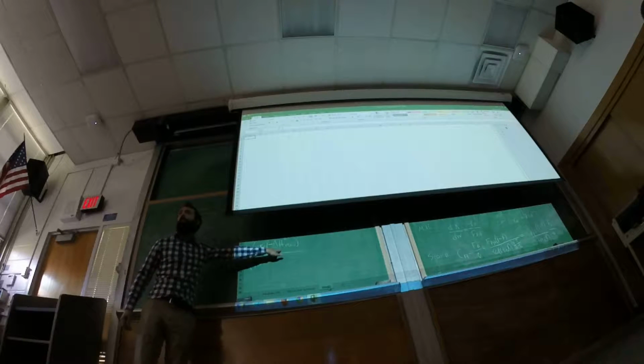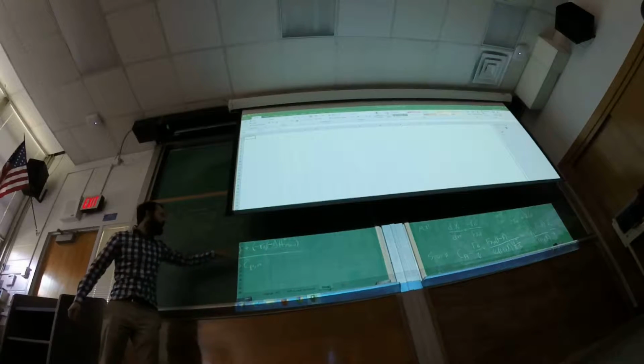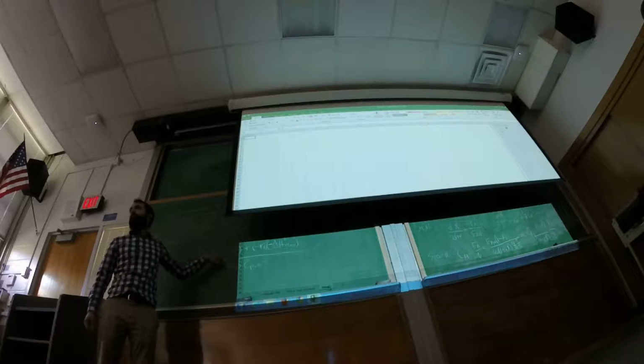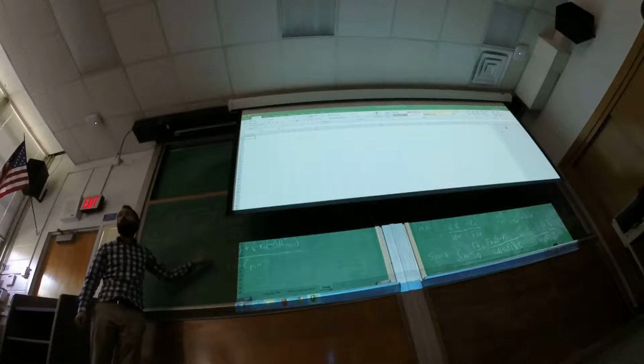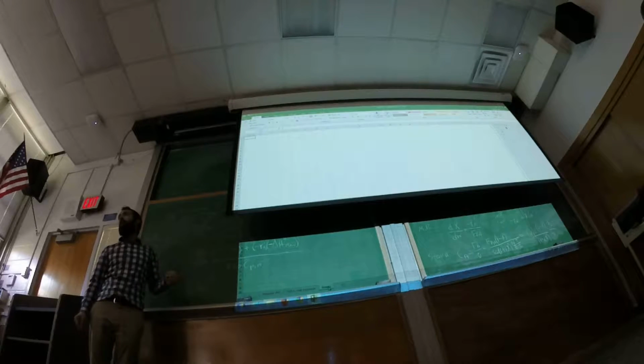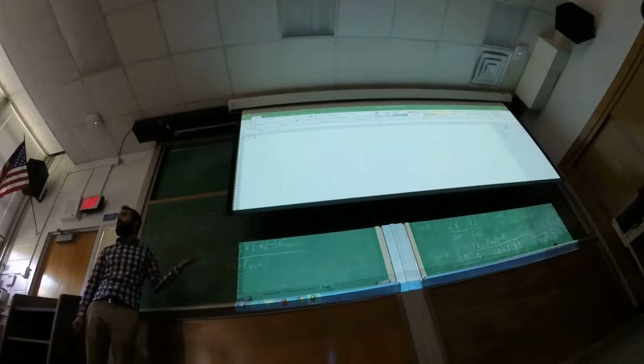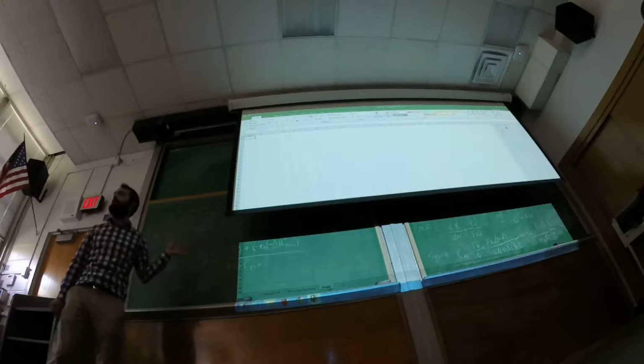So here we're generating heat. Here we're removing heat. So it also depends on what my delta T is, right? But also my overall heat transfer coefficient, the contact area, the density of my solid, all of that also plays a role.